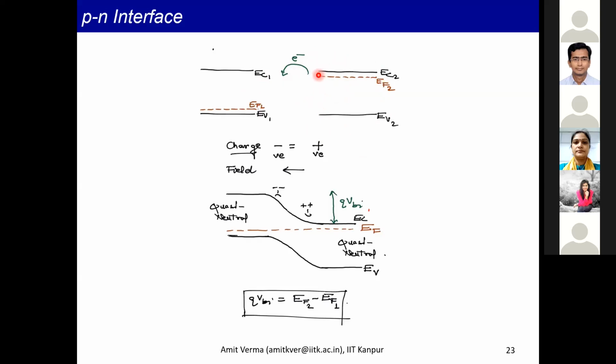That's a slab charge. Similarly, these electrons recombine with these holes, creating a depletion region here, which is negative, which is Na-. Because on the p side, you have charges which are either Na- or p, only two charge components. Holes you are removing by recombining with these electrons. So you have only Na- charge left out, which is also slab charge. For slab charge, you know how the conduction band varies.